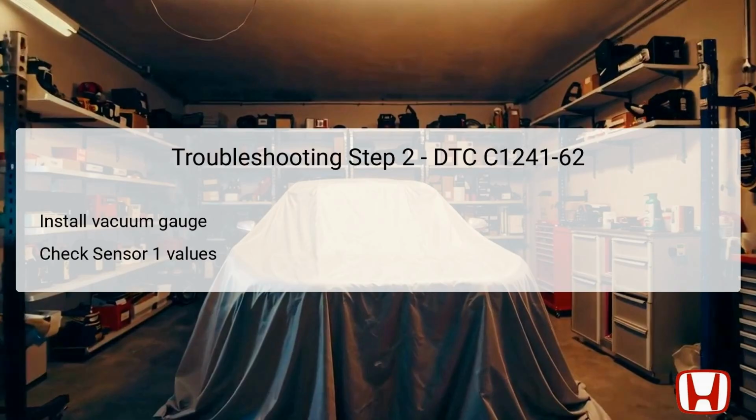Normal operating conditions dictate that the values displayed on the HDS should align with those indicated on the vacuum gauge. A discrepancy in these values signals a potential issue, specifically with brake booster pressure sensor 1. Documenting these results is crucial for subsequent steps in the troubleshooting process.